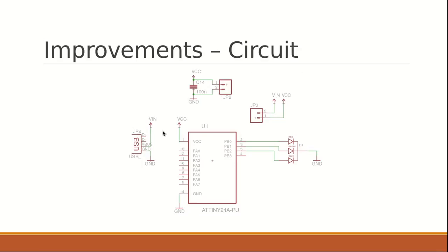Also, VCC is connected to this microcontroller, which is going to drive this RGB LED. So the main purpose of the LED is power indication, but also the microcontroller will let me use pulse width modulation to just kind of phase it in and out of its different colors to give it a cool glow.